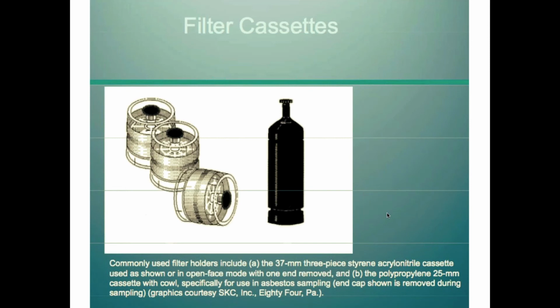Now, PVC filters tend to get a lot staticky and so on and so forth. That's not so bad for collecting dust because you want it to capture the dust. A little annoying when you handle them. Very frequently, there'll be a small radioactive sort of little beta source next to the scale you would use. If you rub it across it, it takes the static away. So a lot of times you see a little pad next to your scale. I'm going to show you a picture of the scale in a moment.